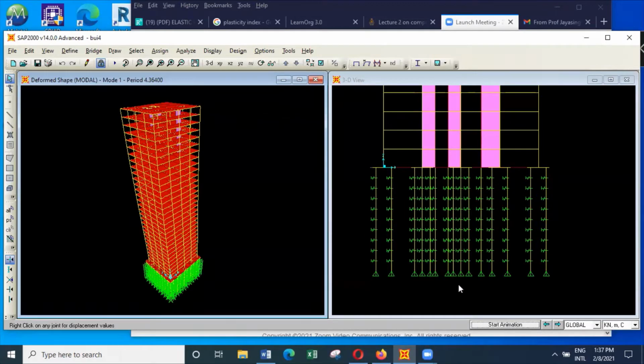So because of that reason, if you want, you can actually apply supports at this level and decide the natural period of vibration, which would be more representative. And when we did the wind analysis, we use these values of natural period of vibration. So the values that you determine here, by assigning the correct mass, you will be able to use it.